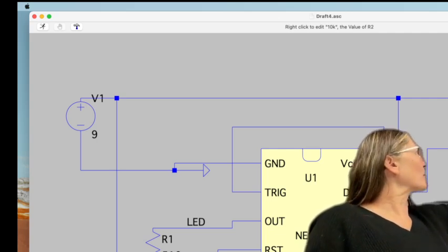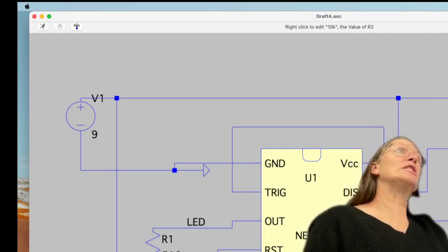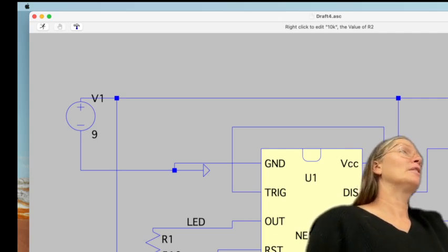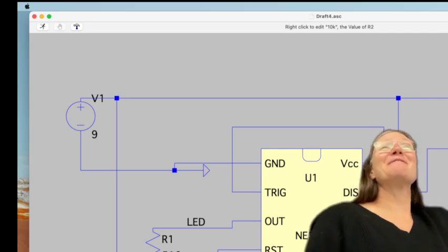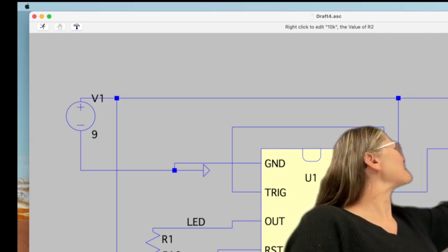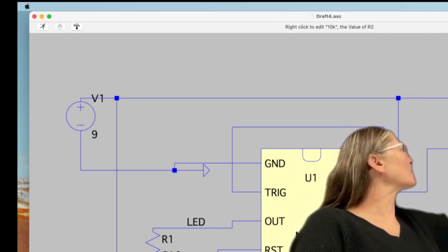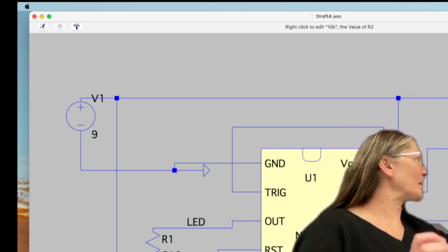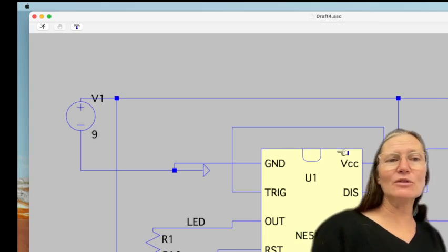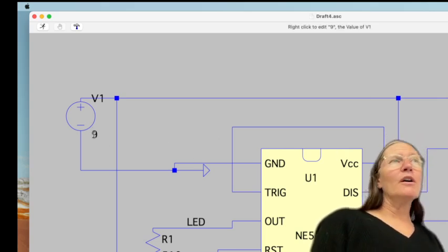So this has a model in there that tells you all the information you need to know about the 555. Each element uses that SPICE model, and when they have a variable, voltage will always default to volts, so it won't have a unit to it.